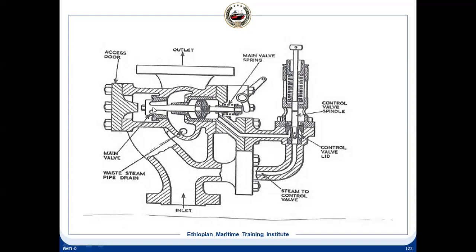And of course, if the main steam stop valve is chattering and feathering over a period of time, all the deposits from the boiler water will start depositing over here. And then when we want the safety valve to actually operate, because of the deposits, it may not operate properly at all. But here, if we find that this is feathering, we'll come to know, because we'll find steam escaping from these vents, from these ports. We know that the valve spring has lost its tension, so we have to renew the valve spring.